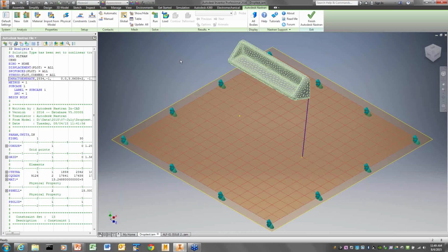So I got a question for you now. When you're basically looking at the vibration of the part after impact, you're trying to see if that matches up with your modal analysis. Let's say it doesn't. What would be the first thing that you would think would be wrong? Let's assume you have everything set up, distance, direction, all that. It matches correctly, but it's not quite right. What would be your first instinct? I'd look at material properties, things like density.